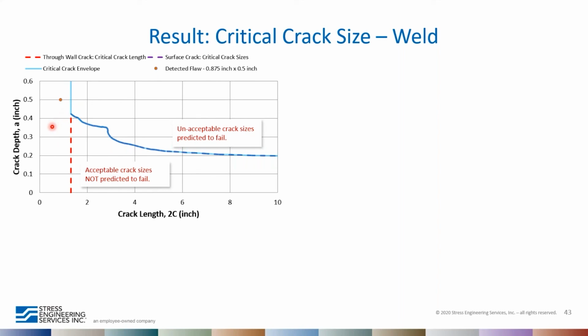And so that explains why this crack, which is in service, is through wall, the system is under pressure, but it hasn't gone critical. There hasn't been a failure. And so, by the way, these results consider the presence of the residual stresses within that weld. Okay, so again, the detected through wall length is less than critical.